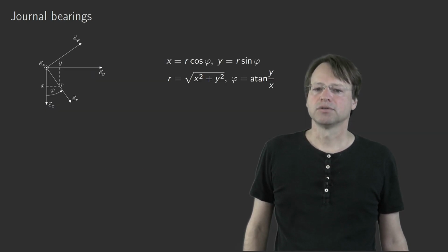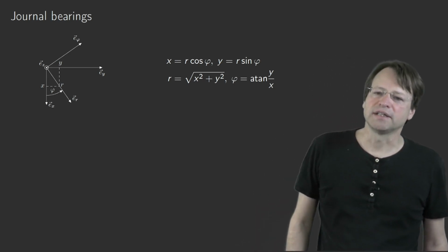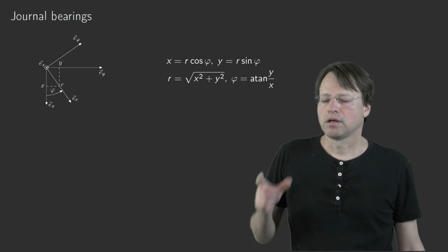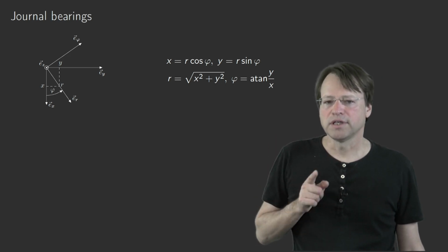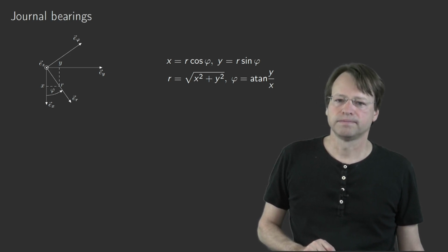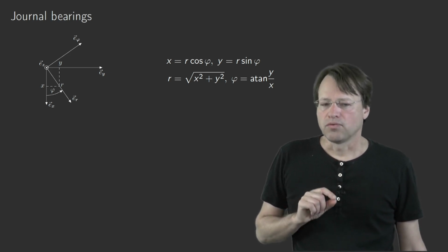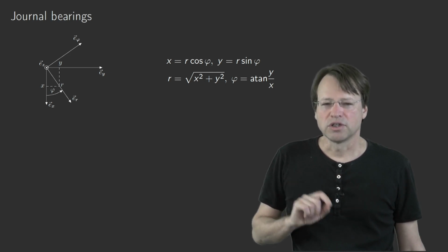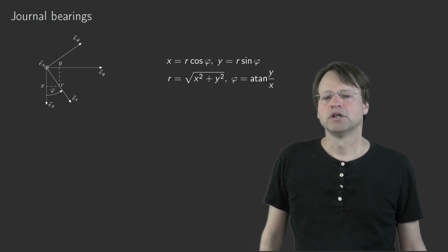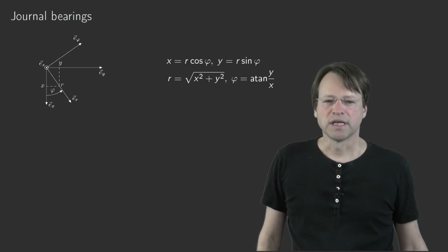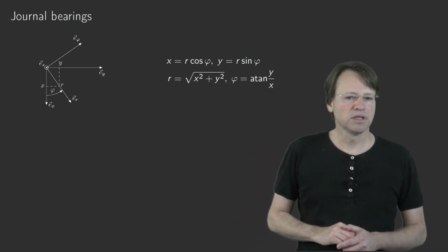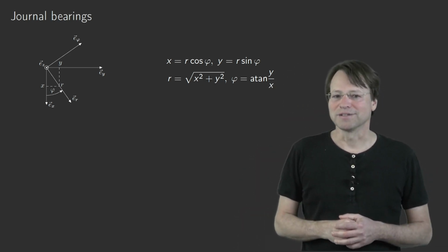Okay, so then let's start to write down the equations that we need, the continuity equation and the Navier-Stokes equation, in cylindrical coordinates. So for this we have to transfer the differential operators div, grad and the Laplacian to cylindrical coordinates. There's a nice theory that allows you to do this, namely it's called tensor analysis.